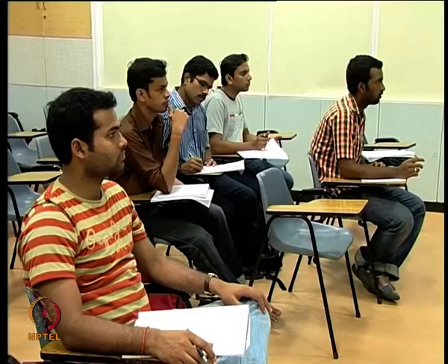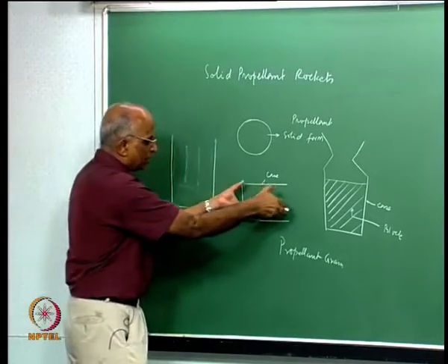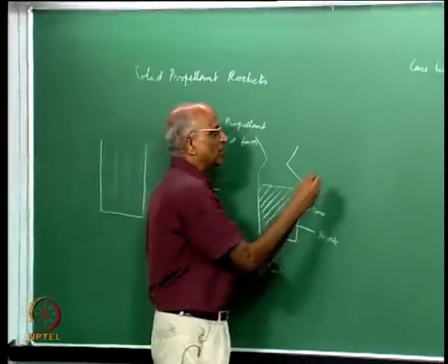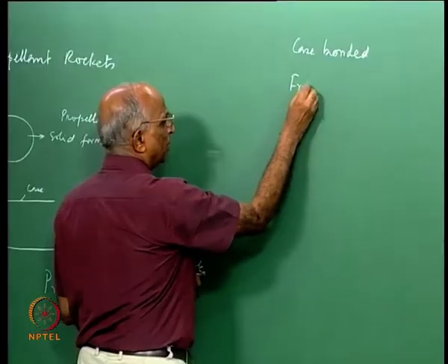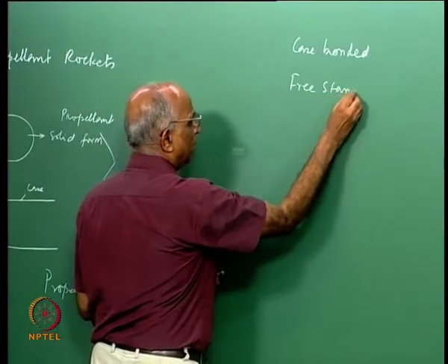It is also possible to make the propellant in the form of a paste and extrude it out, just like we squish out the toothpaste from its container. We could thereafter cure this squished out paste in a furnace and enclose it within a sheath, and then I charge it into the case, in which case it is known as freestanding.